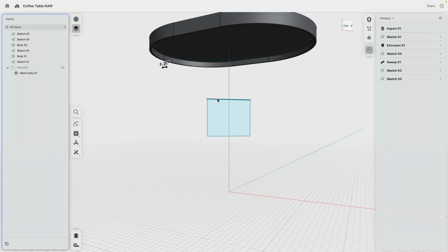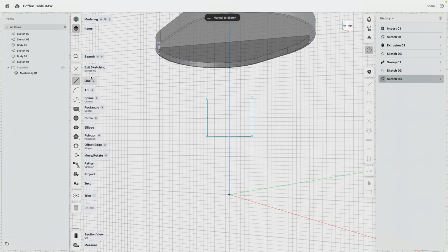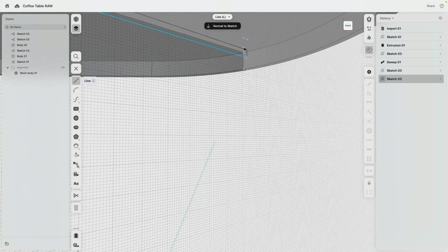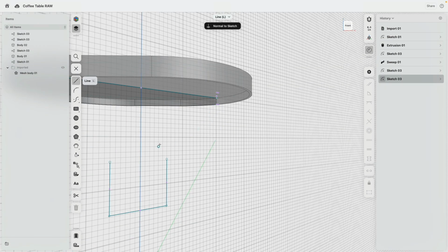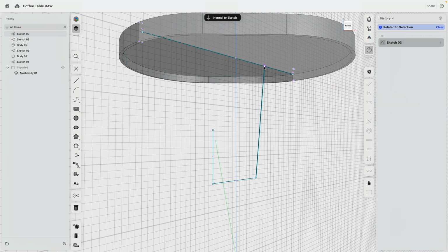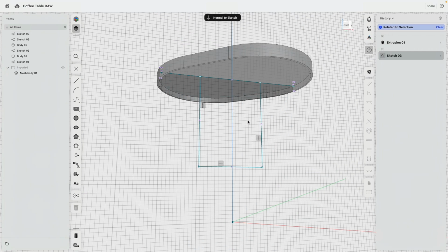Now I'm going to hide my scan, I'm going to delete this top line here. And before I continue, you see there's an intersection of the sketch plane with this geometry. I make this line. So I can then actually connect this one to there, connect this one to there. Very good. Perfect. And then all these lines should be horizontal, vertical.